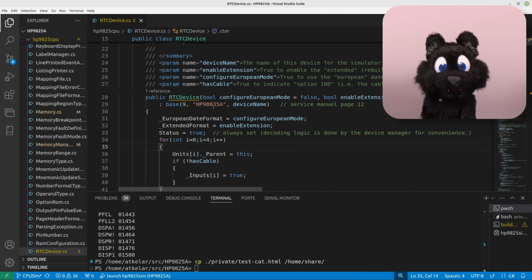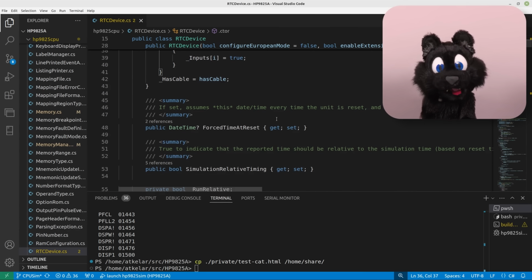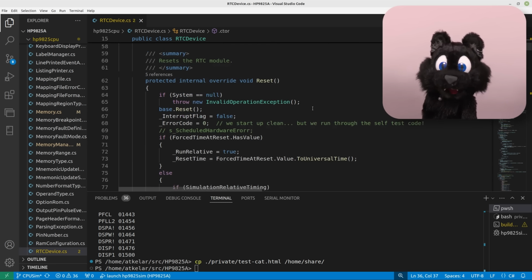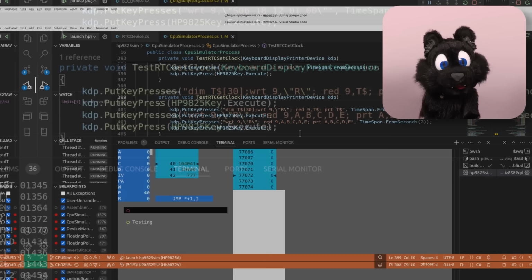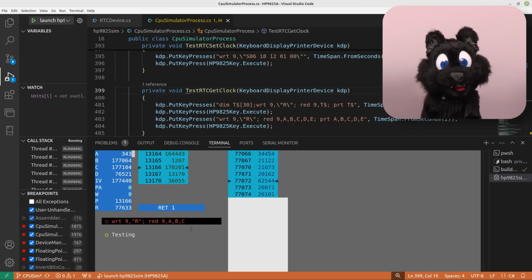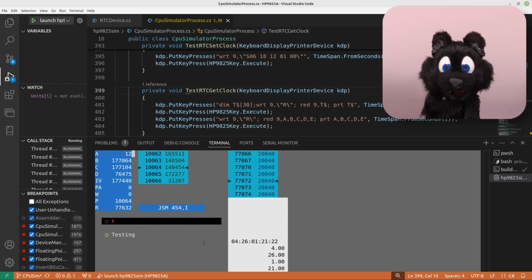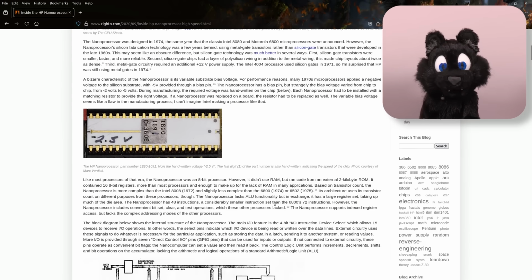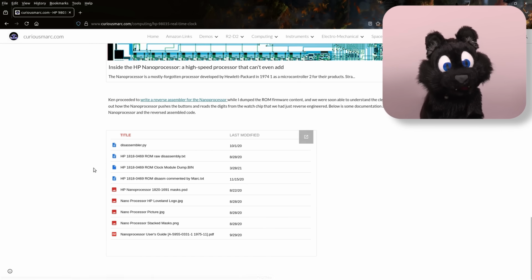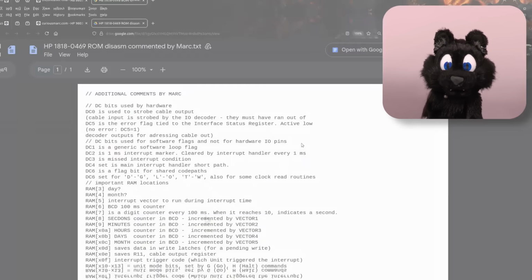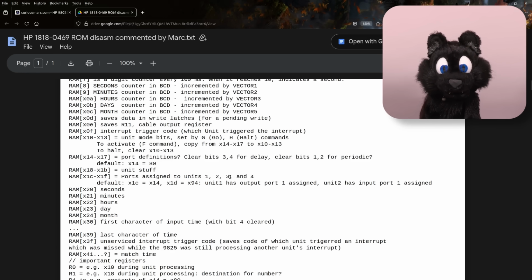Oh, and remember that real-time clock I/O card? Well, I started on that one too. And it does work almost completely already. The simulated version, that is. I'm able to read the current time, set the current time, and even start and stop the timer channels that it offers. What's missing here is the interrupt integration and the factory internal commands. Thanks to Mark and Ken, and unbeknownst to me at first, the firmware code is available. I worked from the manual and schematics myself, but having the internal commands also functioning seems a good idea for a reproduction. Link in the description.